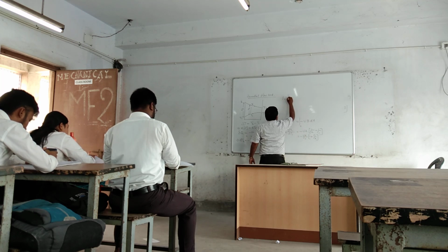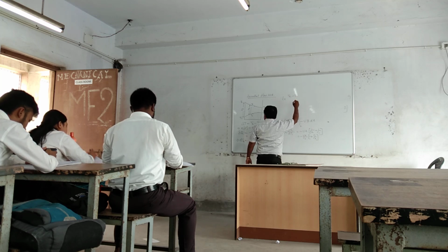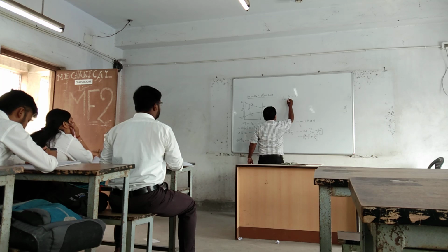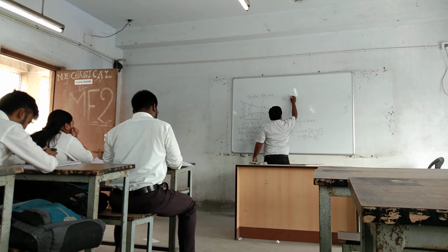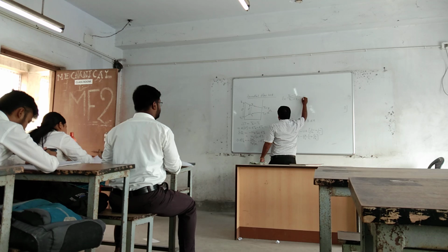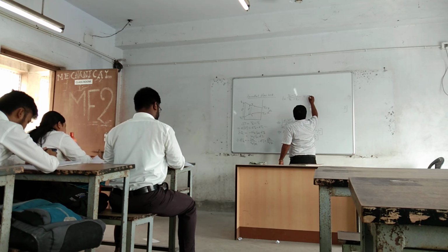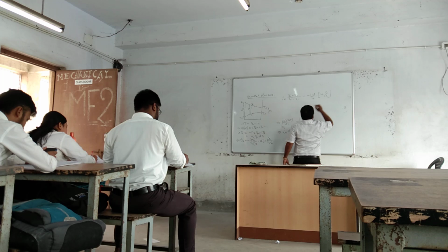So log of THO minus TCO divided by THI minus TCI is equal to minus UA by CC into 1 plus CC by CH.